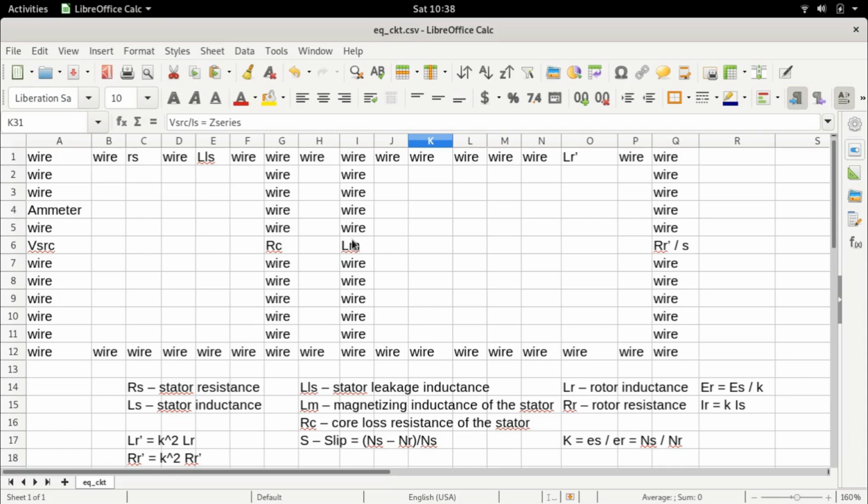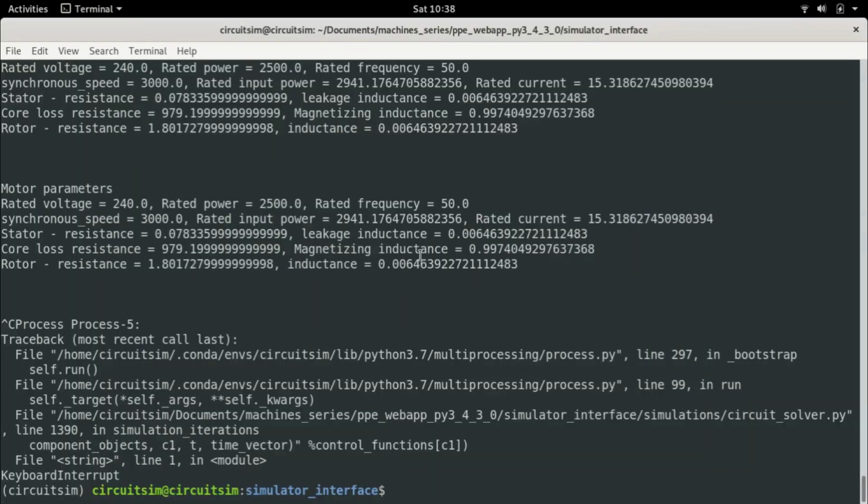If it is prohibitively large, then you will have a lossy machine, because this current drawn will produce ohmic losses as well. So that explains why you have such a large magnetizing inductance, right? Because remember, by basic definition, flux linkage is equal to current multiplied by inductance. So the larger your inductance, the stronger the flux you can produce with a smaller current.